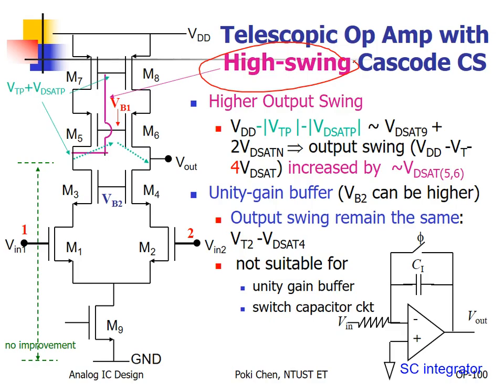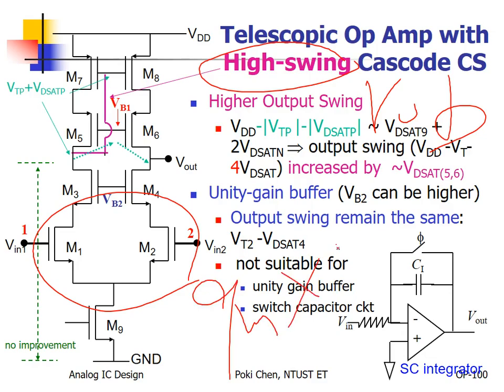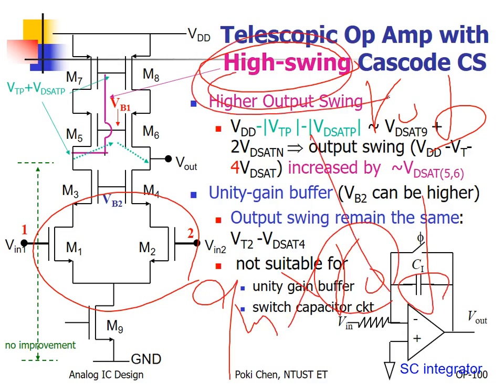If you calculate, you will figure out the output resistance of high swing cascode will be reduced from regular cascode. That is the reason why. Nothing changed for GM, but RO will be reduced a little bit for high swing cascode. That is the background, common sense for analog IC designers.